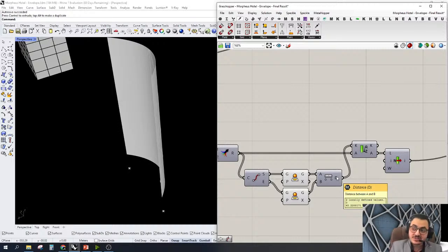So the vertical lines only. If you picked the vertical lines and you projected them, they almost project as a point, or sometimes if the surface is a little bit slanted, they will be shorter than the horizontal curves.